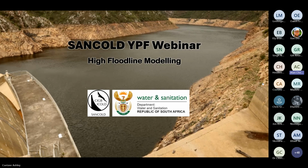Okay, last one, just to add to the presenters. We've done a couple of projects in Africa where the rivers were particularly windy, and we found if your sections weren't close enough, that means not crossing, we found that in the final results, if you didn't do 2D, you got super elevations, which actually messed up all of your design. If you're putting upstream, downstream retaining walls in the river, just say if there was a bend after a stilling basin on a 20-meter high gravity dam or something similar. So I thought I'd just add to that as a comment.